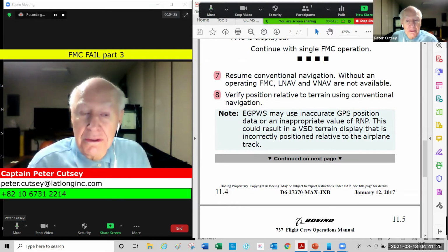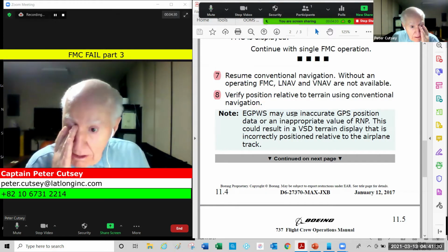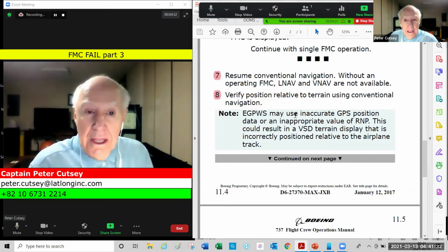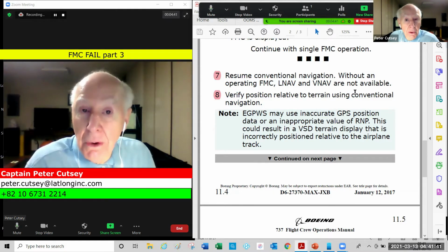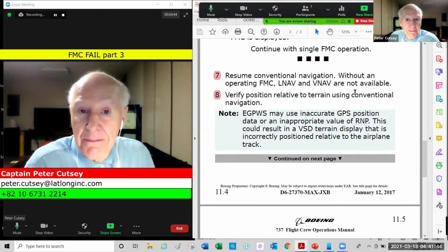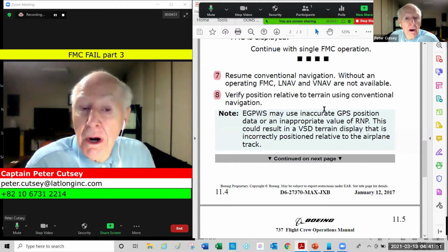We're in the hold, and we're using the autopilot, and we're using the auto throttles. And we're holding inbound on a track of 280 degrees, and 280 is set in both course windows on the MCP. And remember, once we're over the holding pattern, over the MCT VOR, heading select, and then turn to the outbound heading the way I briefed you on in part 2.